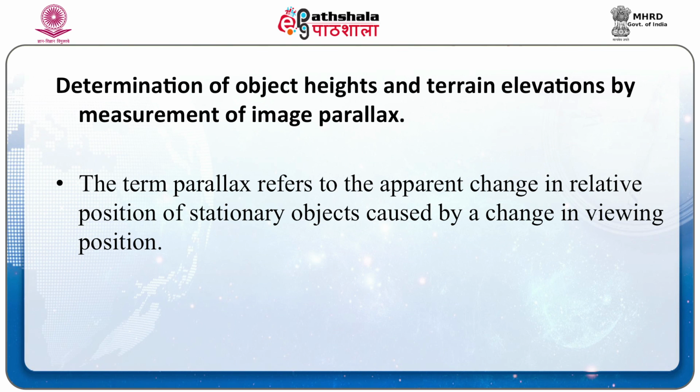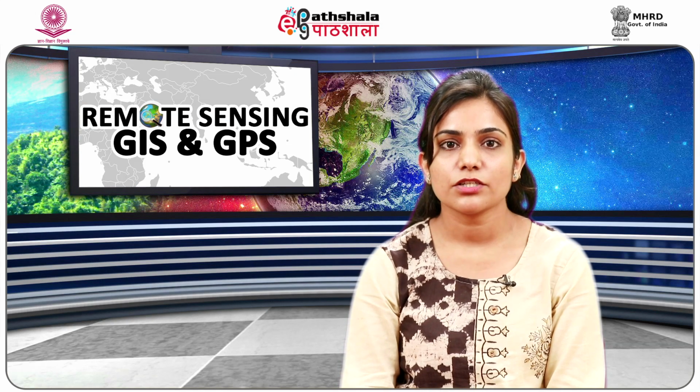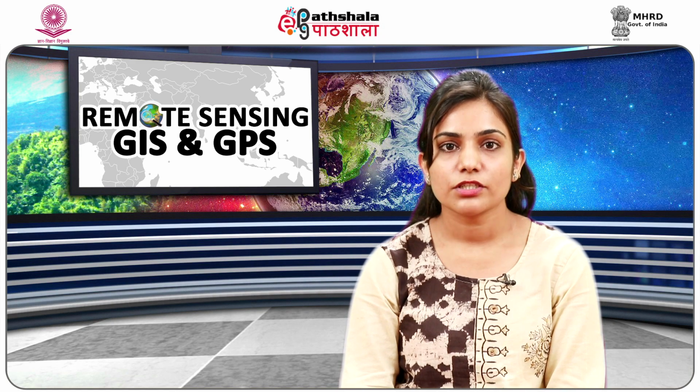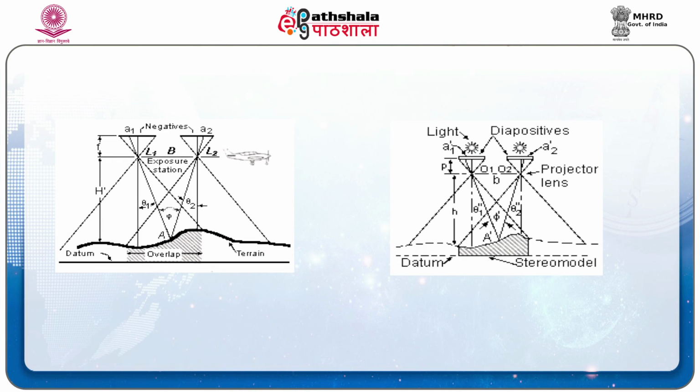Next is determination of object heights and terrain elevations by measurements of image parallax. Image parallax: the term parallax refers to the apparent change in relative position of a stationary object, which is caused by a change in viewing position. The absolute stereoscopic parallax is the algebraic difference, if calculated in the direction of flight, of the distance of two images of the object from their respective principal points.